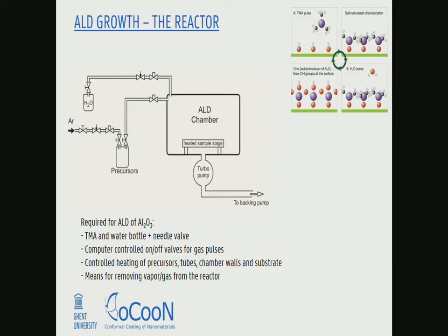So you will need to have an ALD reactor. And overall, ALD is not rocket science. You just need to have a place to put your substrate. You need to be able to heat your substrate because you want to control the substrate temperature. And then you need a way to be able to expose this substrate to different pulses of gases.